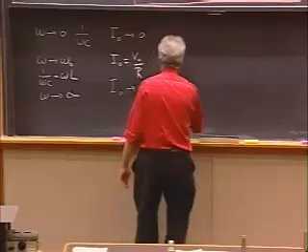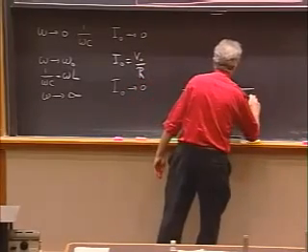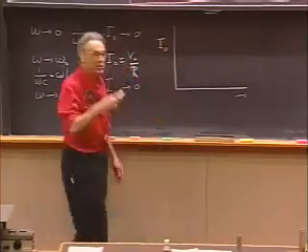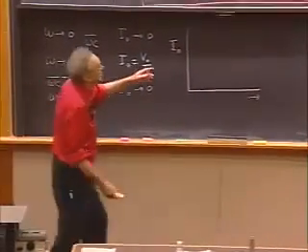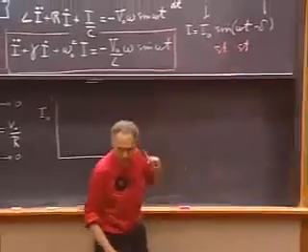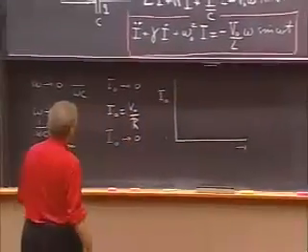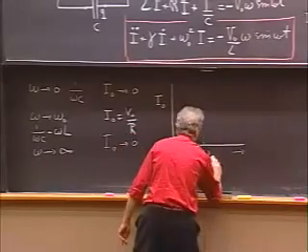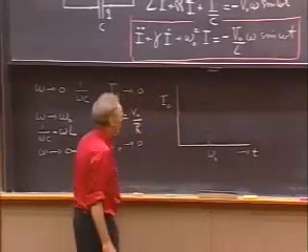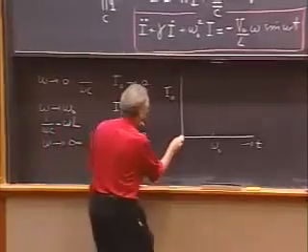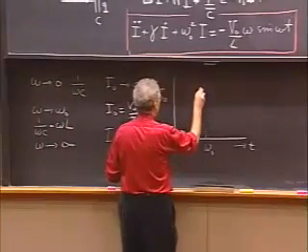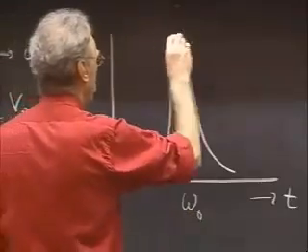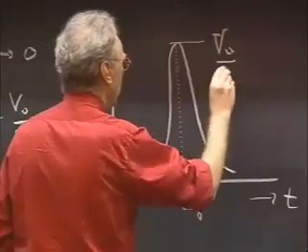So if we make now a plot of the current, I0, that is not the current, but that is the maximum possible current. It is that I0 that you see here. Without having solved it, I can look now at what it's going to do. Exactly at omega 0, it will go to a maximum. It will start at 0, will go to a maximum, and then it will fall off to 0. And this value here is V0 divided by R.